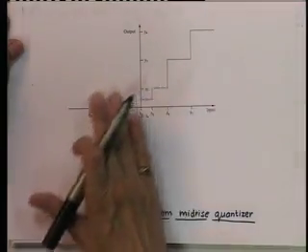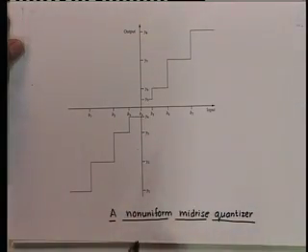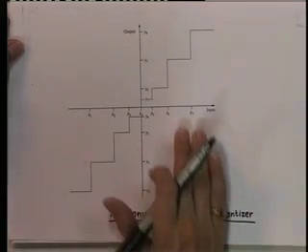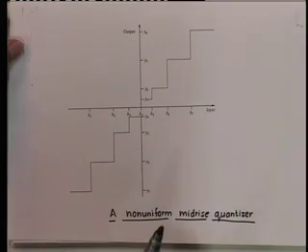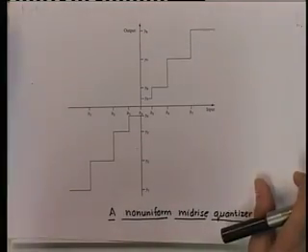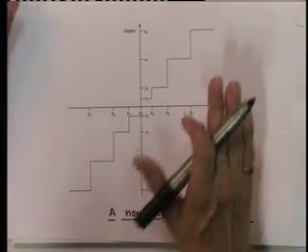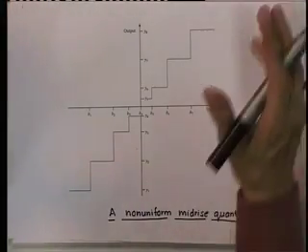So, while a non-uniform quantizer provides lower average distortion, the design of a non-uniform quantizer is also somewhat more complex. So, the basic idea is quite straightforward. Find the decision boundaries and reconstruction levels that minimize the mean squared quantization error. Now, let us look at the design of such a non-uniform quantizer in more detail.